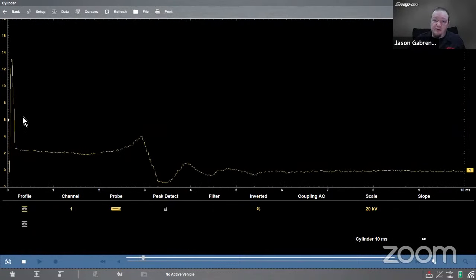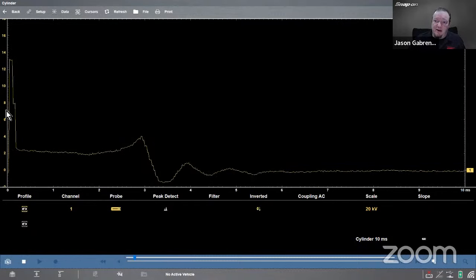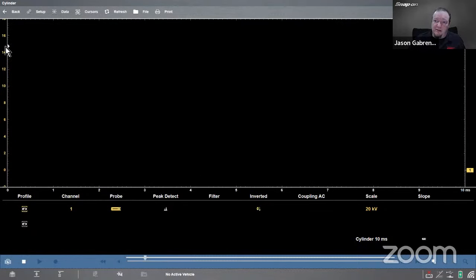Now, as opposed to single cylinder, which I can look at one cylinder on the screen and kind of move it around. This one is a single cylinder. And then you'll see my trigger point here is this arrow. Now, if you ever have trouble getting an ignition pattern on in any of these views, use this triangle. Bring it down inside the pattern, it'll show up. If it's ever outside the pattern, it'll go away, and you won't see it at all.